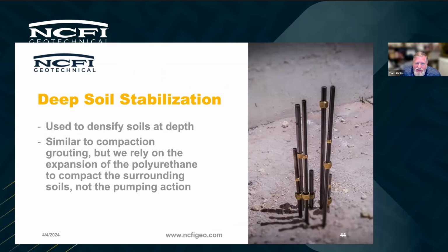Deep soil stabilization. So this is a little bit more advanced stuff. This is where we're going to need to have the soils information in order to design a proper solution. What we're trying to accomplish with this is similar to compaction grouting. We're trying to densify the soils at depth. We rely on the expansion of the polyurethane instead of the pumping action of the actual concrete pump.